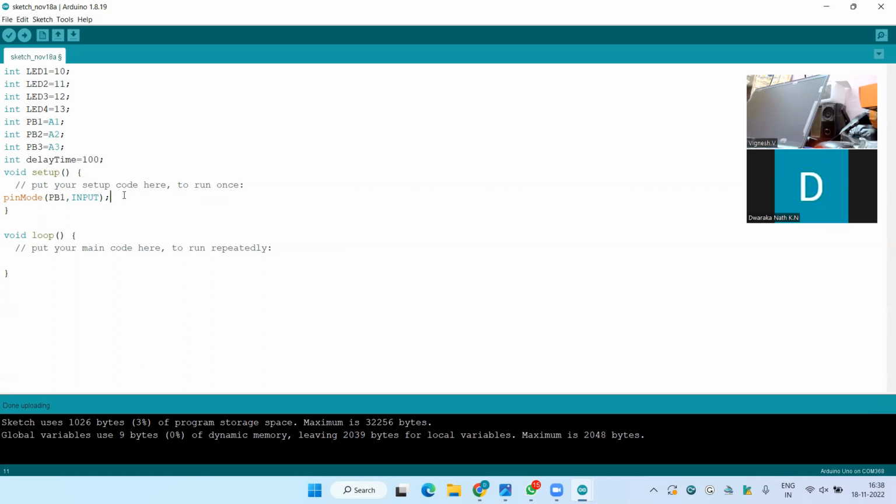In order to see the serial monitor, we need to enable one more thing. We need to enable the serial monitor. For that, there is a command called Serial.begin(9600). This is one baud rate. At that baud rate, the serial monitor will open and show us the input data here. So I'm opening this one.